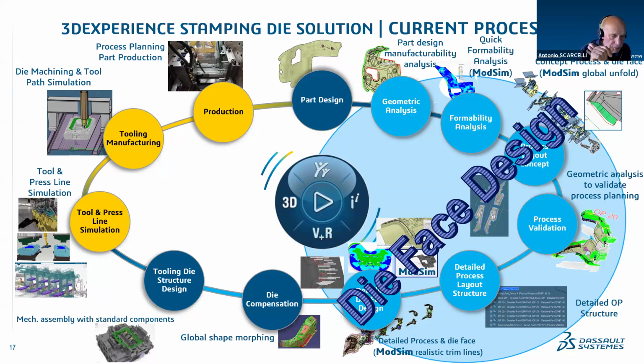If there is some problem, because sometimes when you replace a part by a new one, maybe you will have an additional cutout, the system doesn't know in which operation you want to do this cutout. Maybe there will be a different position, sorry, a different axis system for the CAM, so you need to validate it.